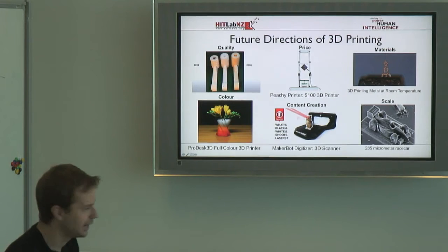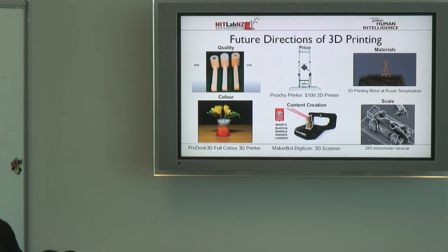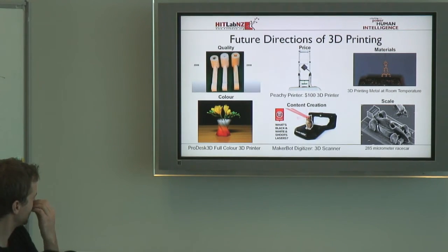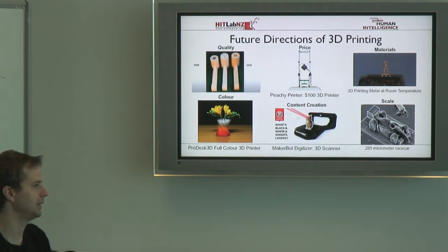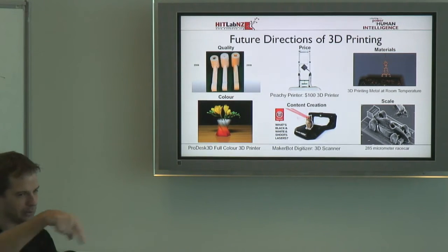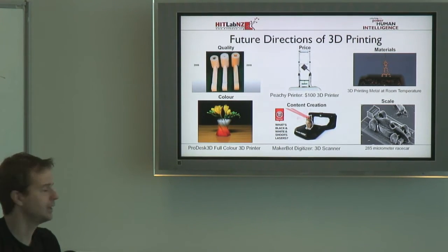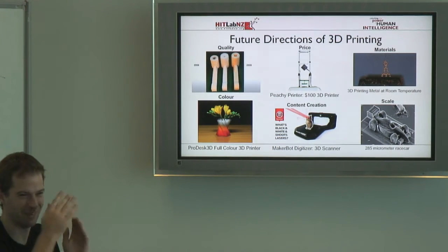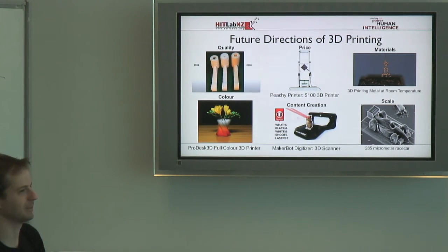Some of the other things as well, carbon fibre is a big one, which everyone's looking at doing. The challenge with carbon fibre is that it gets its strength from its structure. So you need to print down a layer and then print the carbon fibre as a weave within it. But there are people who are working at that. I remember about 2 years ago, they said they had the first carbon fibre 3D printer, but they sort of missed the point because they weren't actually weaving the carbon fibre in. I think they were just chopping up carbon fibre and melting it. And it's like, well, carbon fibre gets its strength from the fact that you weave it through so it holds its shape.